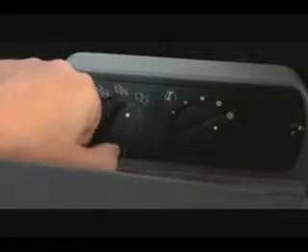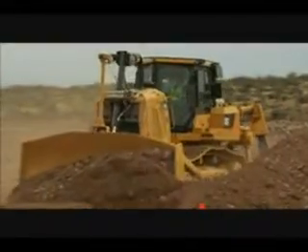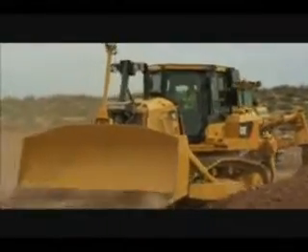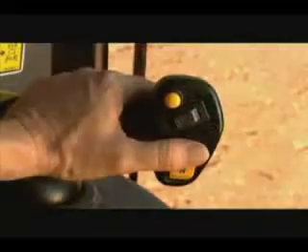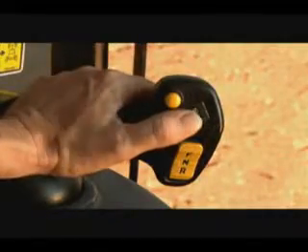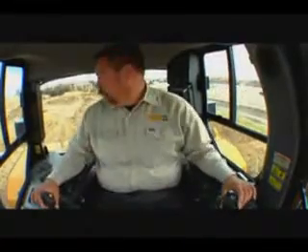Now, when you turn the bidirectional mode switch to the 4th position, your program speeds will show in the LCD display, and you're ready to operate at your preset speeds. You can increase or decrease track speeds at any time by using the thumb wheel. The speeds will return to their pre-programmed values the next time you shift between forward and reverse.